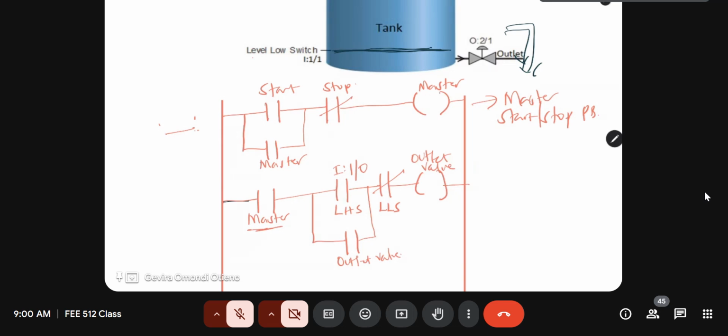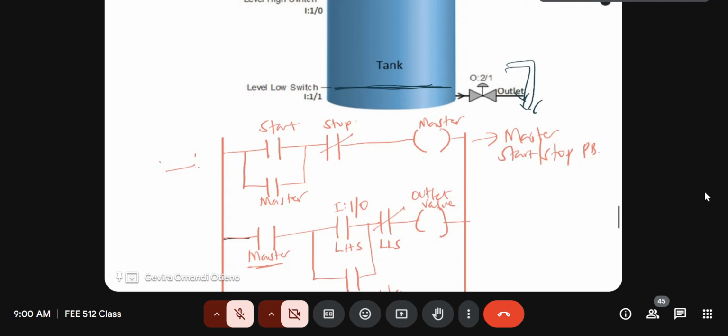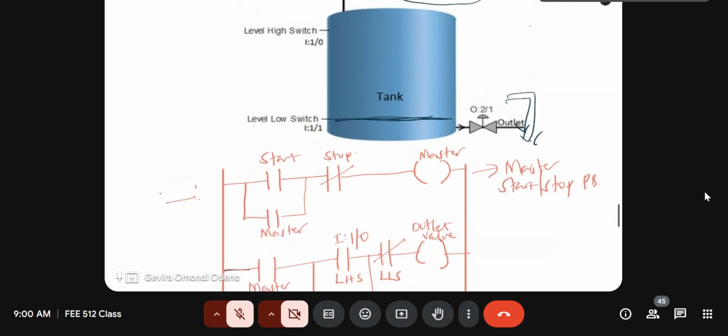So that's important to remember, because if we don't put that latch there, then the emptying will be happening throughout, and filling also wants to start happening throughout, but it is controlled. We fill, after we fill, we empty. When we are filling, we are not emptying.